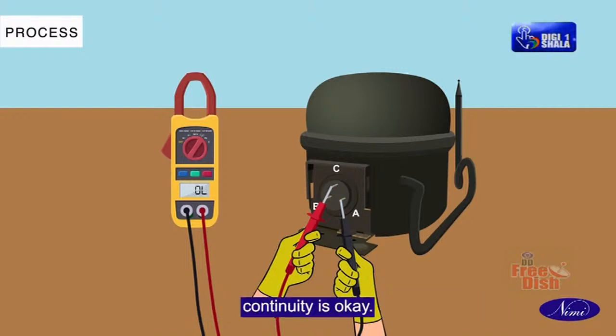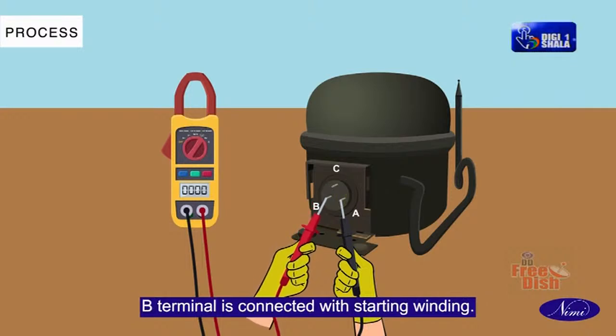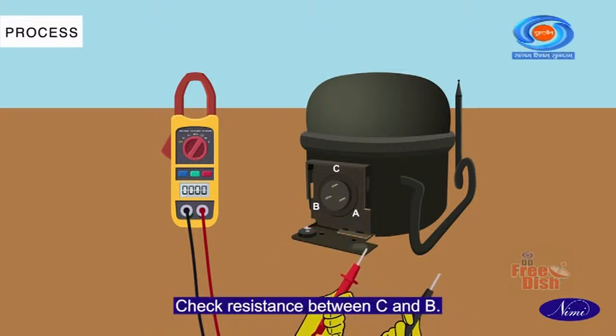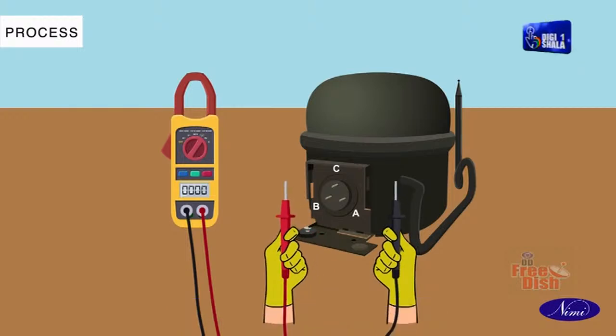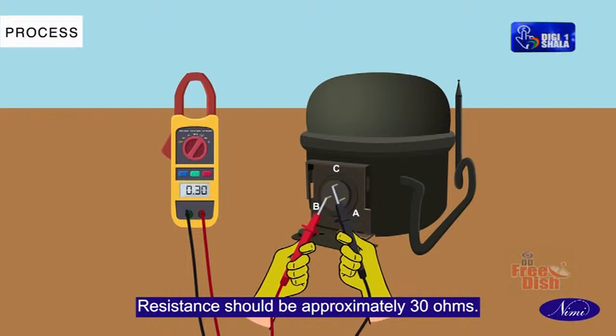Continuity is OK. A terminal is connected with the main winding. B terminal is connected with starting winding. Check resistance between C and B. Resistance should be approximately 30 ohms.